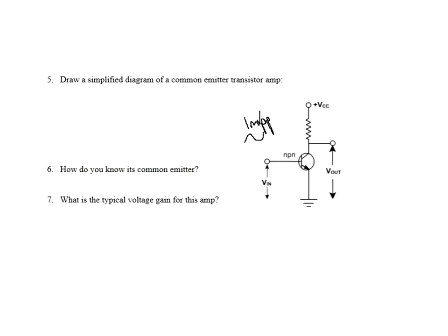And if I have a good power supply right here, say we'll make it 100 volts, just make it a really good one, I might get out of this 20 volts peak to peak. And we know that V out divided by V in gives me my voltage gain, AV. The voltage gain. The amplification factor, A, of the voltage, V. That's V out over V in. You don't have to do a calculation. I'm just telling you how you find it.